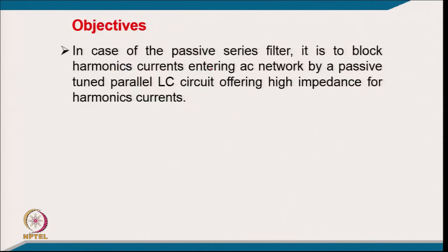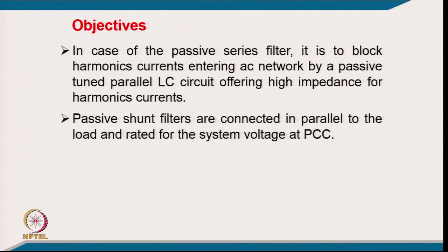And the series filter of course blocks, but ideally it should give 0 impedance at the fundamental frequency. It offers certainly low impedance, but this is inductive, because you can understand that at the fundamental frequency the reactance of the capacitor which is connected in parallel with the inductor will become high. So, the fundamental current will not flow that much into the capacitor, but the major current will be flowing through the inductor. We will look into the circuit when we come to it.